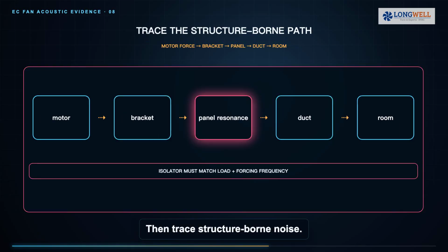Then trace structure-borne noise. Motor force travels through brackets, panels, and ductwork, where a panel resonance can amplify it. Isolators, stiffness, and mass must be selected for the forcing frequency and load. Soft mounts are not a universal fix, and they must not compromise alignment or safety.